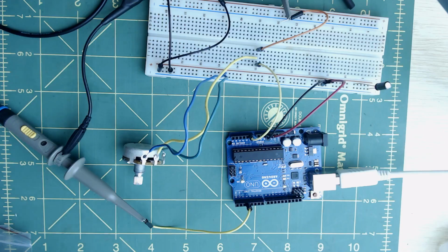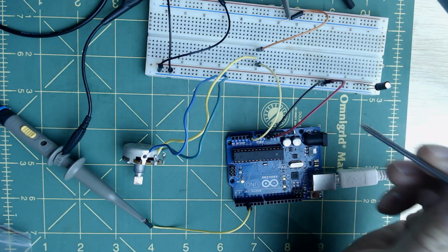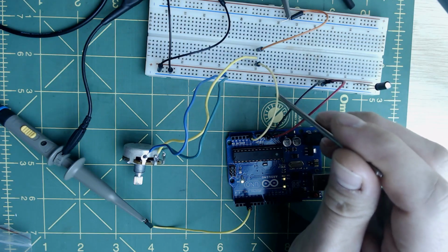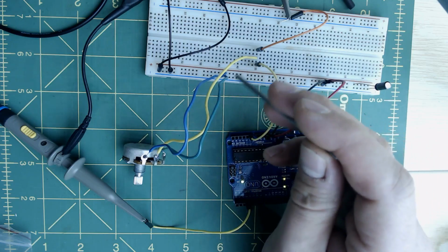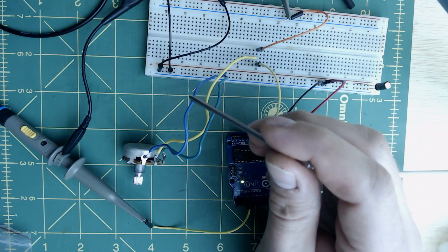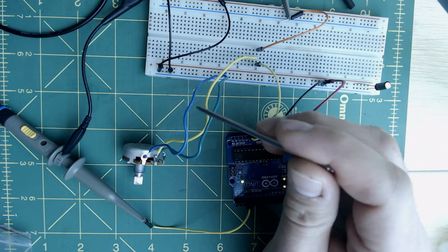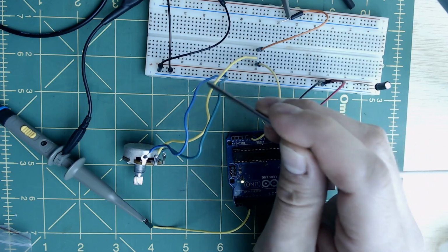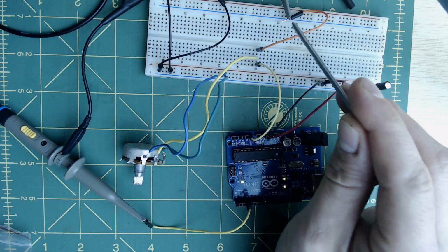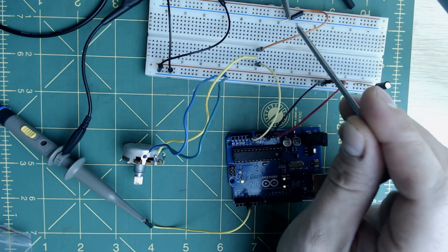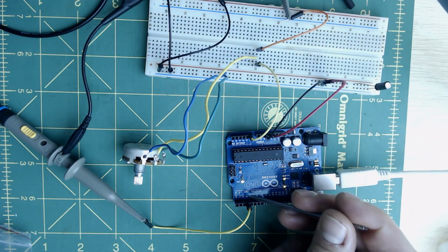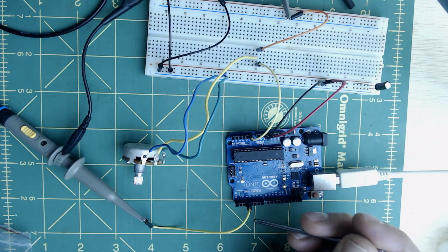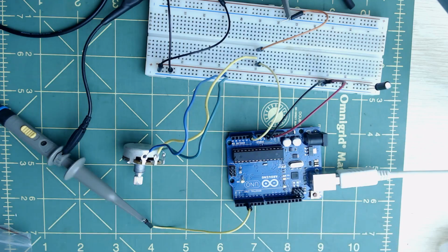What I've done here is I still have our analog input set up from last time. We have our analog input on A0 connected to a potentiometer between 0 and 5 volts. So we have 0 volts on one leg, 5 volts on the other, which creates a potential difference of 5 volts between the two legs. Then our wiper is connected to our analog input on A0. This is one channel on the oscilloscope so that we can read that voltage. And then here on pin 3, I have connected another channel of the oscilloscope so that we can actually see the PWM signal.